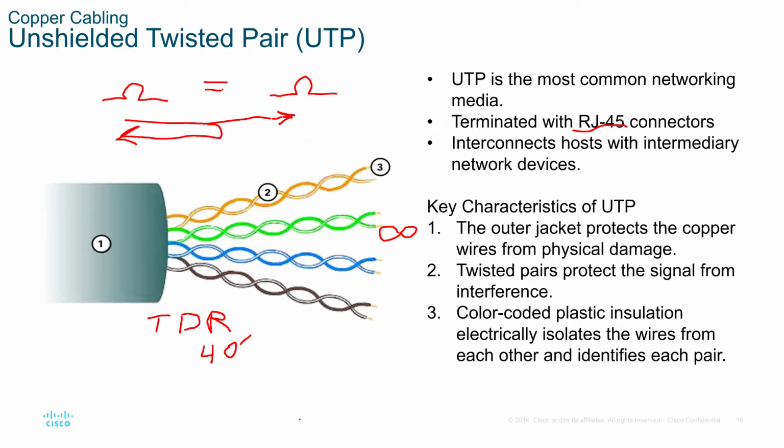You may have seen the phone company digging up the street looking for a break in the cable. How do they know where to dig? They went to the endpoint and they put a time domain reflectometer, and it told them the break was 100 feet from where they were. And that gives them a good idea of where to actually dig. For fiber cables, we use the same process, except we use an optical time domain reflectometer.